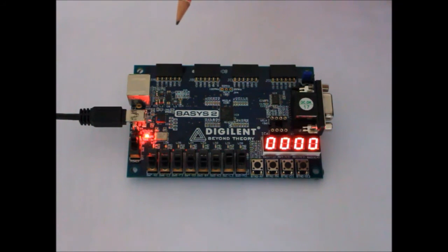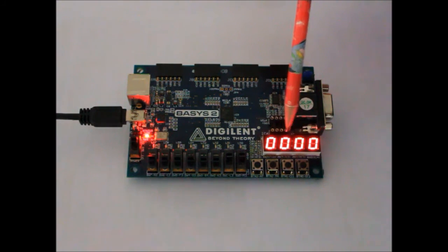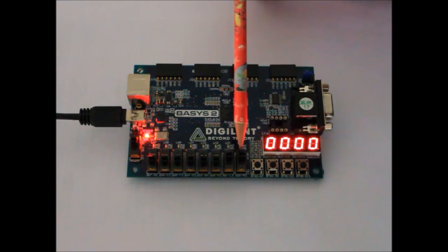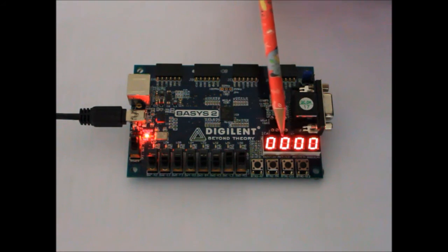Okay, so what we're looking at here is the BASYS 2 board, and in particular the FPGA Spartan 3E chip in the middle here, which is now being programmed up with our circuit design. Now, as discussed earlier, the circuit is designed to give me a hex counter over here, and I've programmed a couple of the switches. So switch 0, which is this switch here, is controlling the direction of the count, so whether it counts up or backwards.